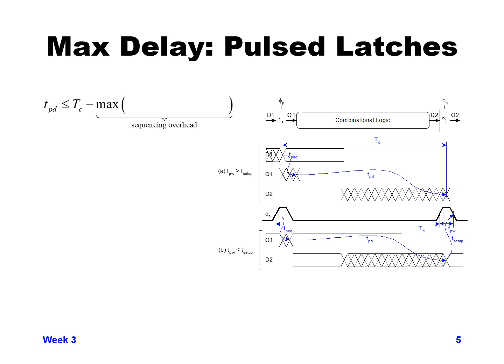And that propagation delay, after we get through that for the latch, we go through the combinational logic, and we have T propagation delay of combinational logic. And finally, when we get to the end there, we want to get to the end around the time that the clock is rising, and that would be our cycle time.